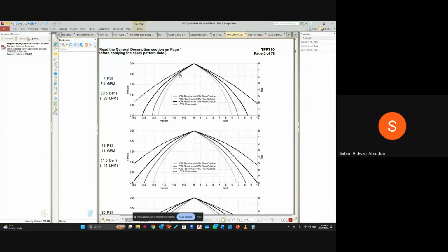Can I answer? Okay, so when you want to classify a building to a hazard, you don't just look at what is happening here. You don't just look at the spaces. You look at activity, occupancy, and storage. In fact, when we were doing National Theatre, we even sprinkled the ceiling void. I'm very sure you might not have heard that one before. Sprinkling of the ceiling void, because the code says when the ceiling void is more than 1.5 or 1.2 meters, you should sprinkle it, especially when you are sprinkling the space below it.